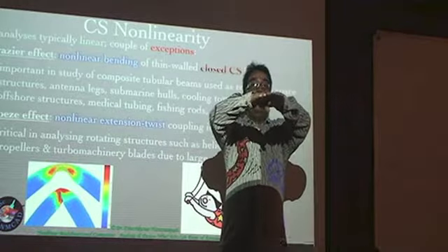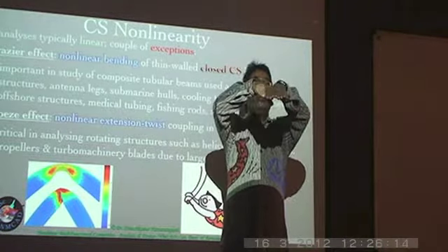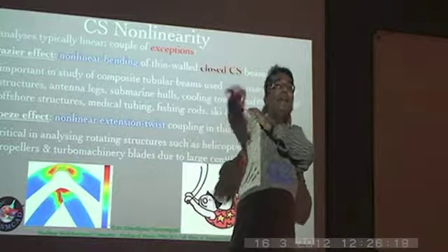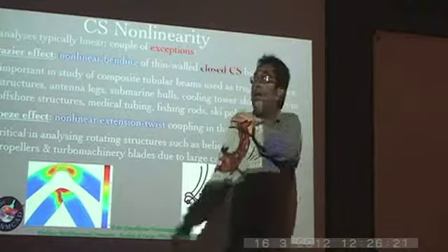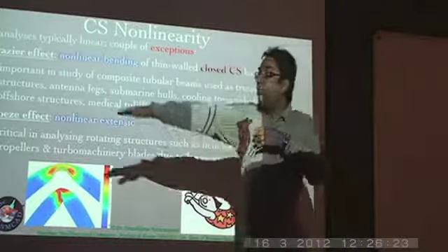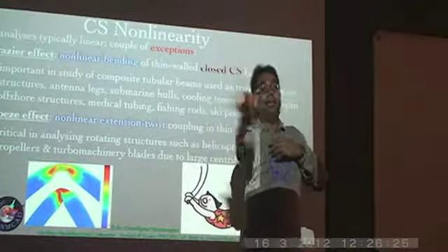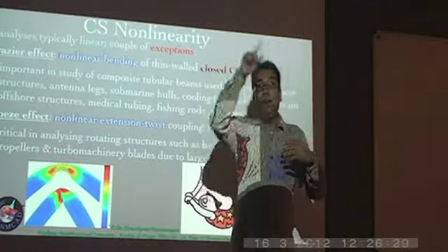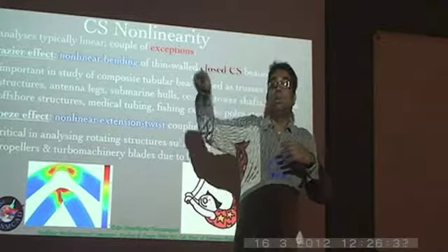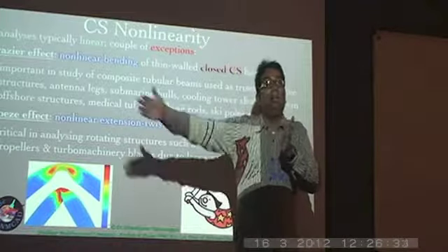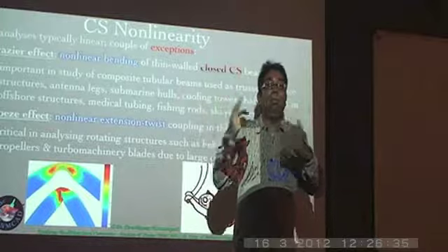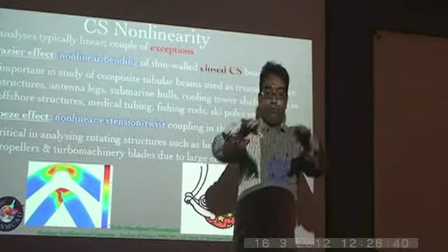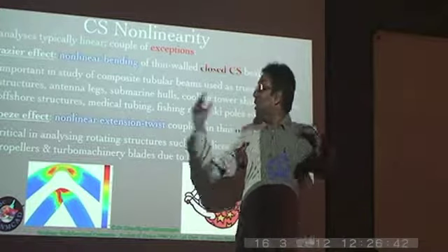So the end effect is that the rotor plane seems to have tilted like this, but what is actually happening in terms of the beam is that it's bending. It is bending down here and bending up here, and somewhere in between here, and it is cyclically undergoing that particular loading of bending. The bending varies sinusoidally, or as cosines of different harmonics, the primary being the same as the RPM of the rotor itself. Now, where does the twist come in?